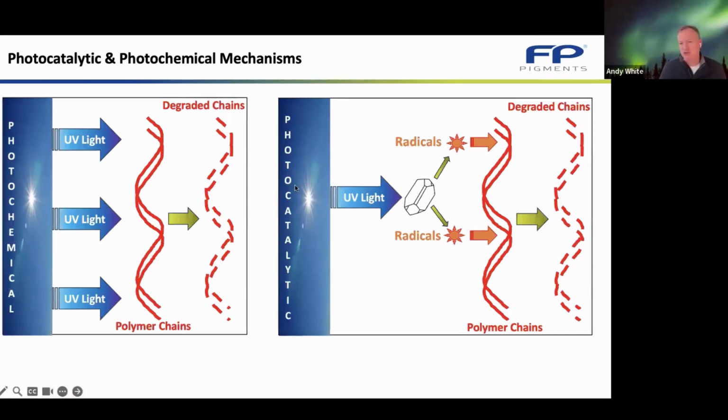However, as the polymers become more durable, the titanium dioxide itself has a part to play in causing the degradation of those polymers. The TiO2 can be the host for forming free radicals, and those free radicals go on to break down the polymer chain.